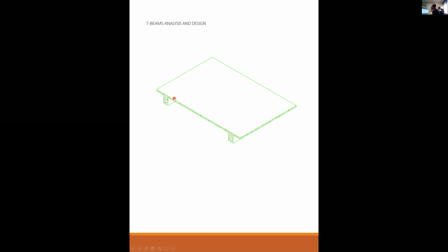So we can use the concrete that is really spanning this way, and we can turn it this way and use that concrete, at least some of it, for the design of the beam. All of this concrete here does a wonderful job of being the compression member for this beam. That's why it's called a T-beam. We're using some of this concrete up here to help in the design of our beam.